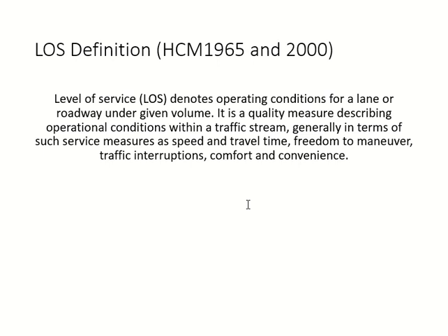And comfort and convenience, how comfortable and convenient you feel while driving. All these things are part of level of service. Instead of having a number for each one of them, so you have six or seven different numbers, and some of them are not even quantifiable, we have one level of service which tells you the overall condition of the traffic.